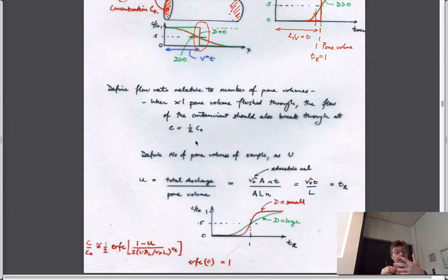So, if we know then that part of this big, large-scale structure of the aquifer is going to be important, the next logical thing to say is, well, we could do some field experiments. And so field experiments would be just like, hopefully you learned in 452, that you drill a well, you start sucking water out of the well, and from a prescribed rate at which you pull it out, you have another well some distance away from it, and you look at the rate at which the water level is drawn down in that other well. And from that drawdown rate, you can fit that response to be able to figure out exactly what the appropriate permeability would be to that system.